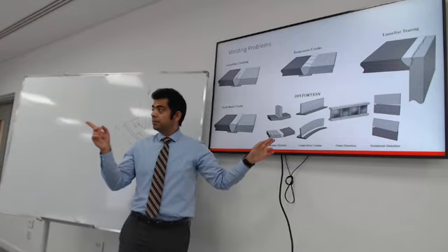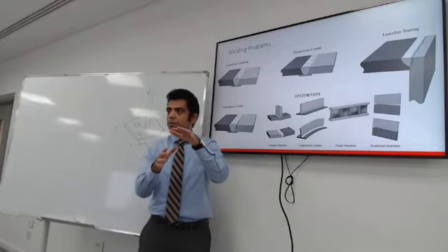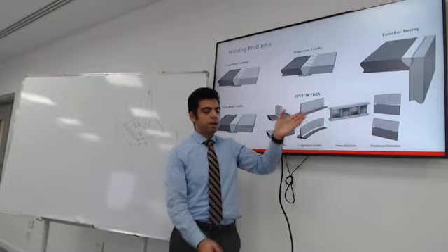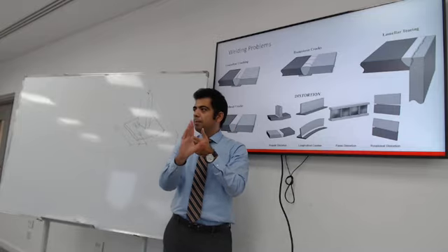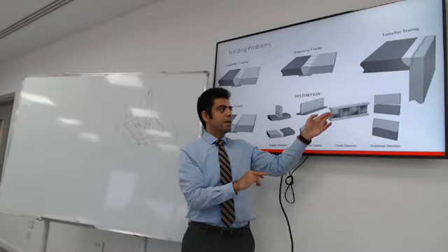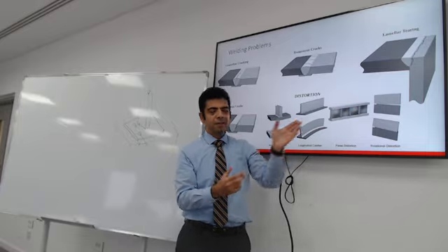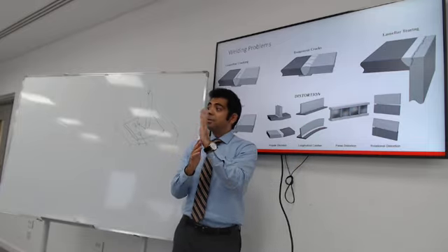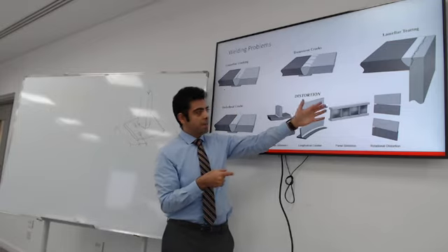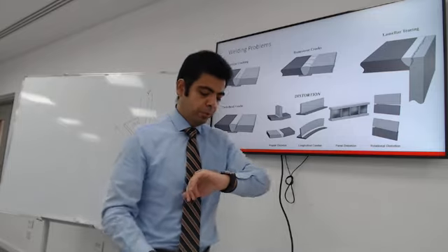Too much heat, this is the point that we were talking about, will cause distortion. Remember the check for the shear capacity in the web of a beam? The design might dictate some stiffeners. These are the vertical plates that are stiffening the web. The web is usually very thin. If you apply too much heat on it, it might warp and distort like that. So that could be a problem from welding.